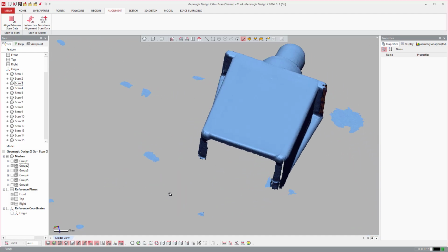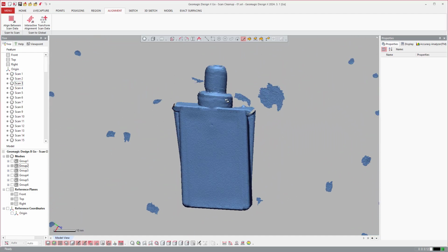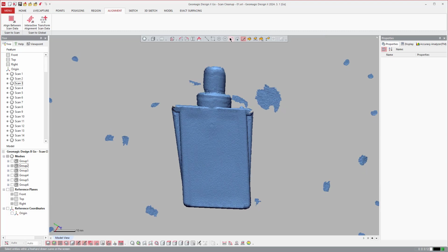And then do the same thing I did before where I can window in. This time, let's use a different tool just to show something different. Use the polygon tool. So I can select using a polygon tool. And when I'm in the polygon tool, I can't really rotate. If I do, then it's using the polygon from this specific perspective.